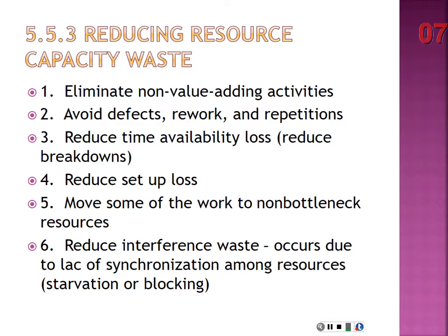Okay, reduce setup loss, meaning when I transition from one type of product to another, it takes a certain amount of time to change over the equipment. I can remember when I first started at the custom plant, we had these very complex molders, right? And the changeover time from one type of door product to another type of door product was hours, right? And so what they were able to do is they were able to reduce that down to minutes as opposed to hours, okay? So again, you're looking for ways to reduce that setup loss, right?